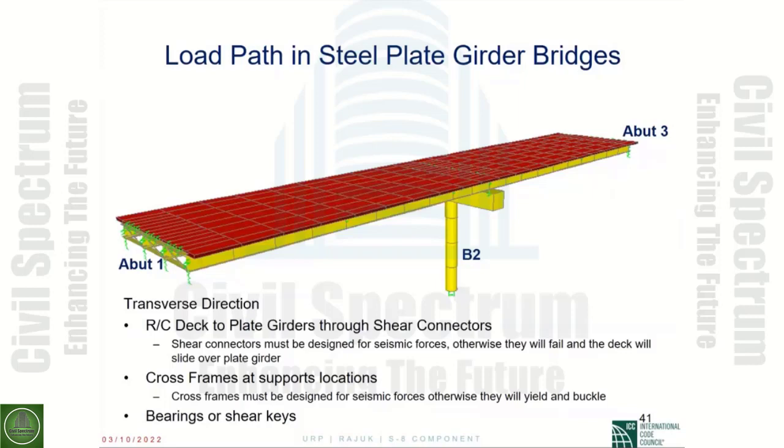There are people who are really concerned about fatigue at the negative moment for the superstructure, so they tend not to put shear connectors there because of the worry about the welding on the top flange of a plate girder.